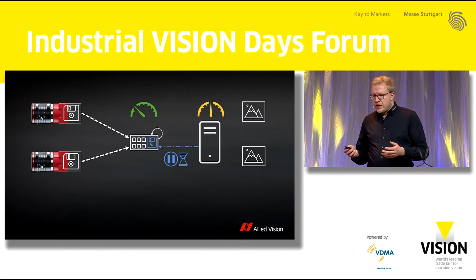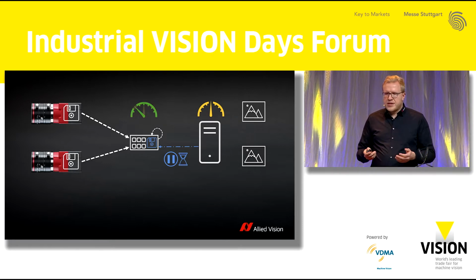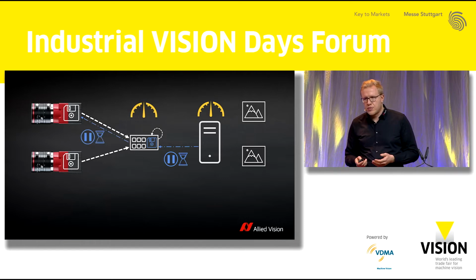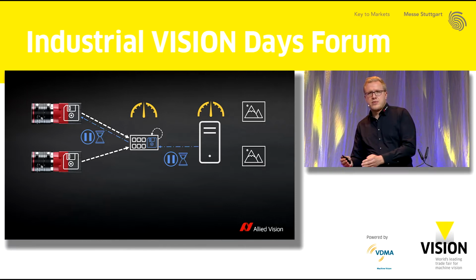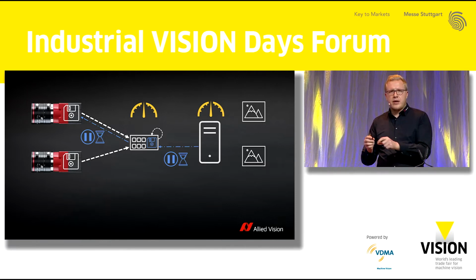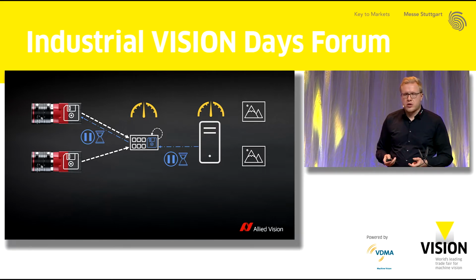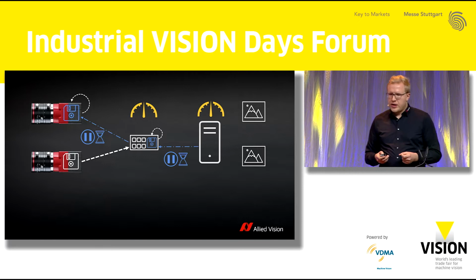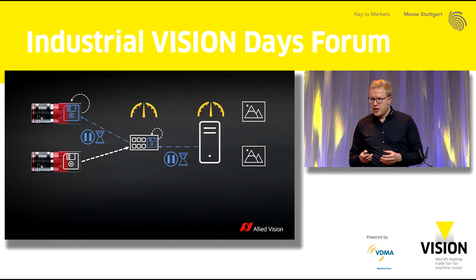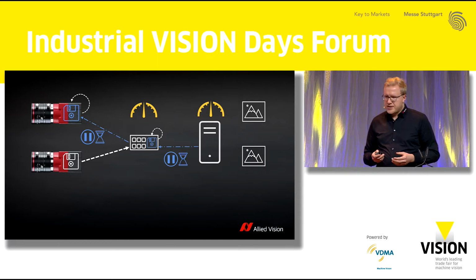And then an interesting thing can happen. It can do the very same thing. It can send a pause command to the camera itself. And it's really important to note here that flow control is based point to point. So any network device between the host and the camera can send such a pause command. And now the camera will buffer the incoming data from the image sensor. And the good thing here is most of the time cameras have a much larger buffer than the network devices have.